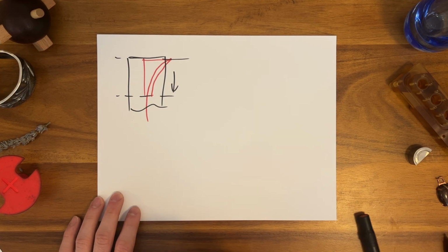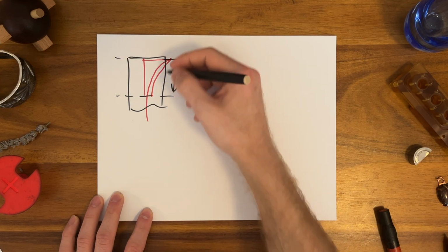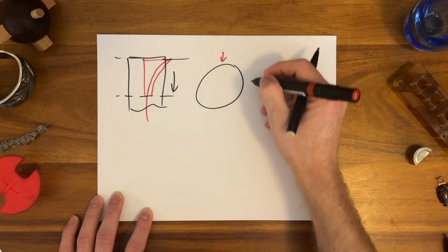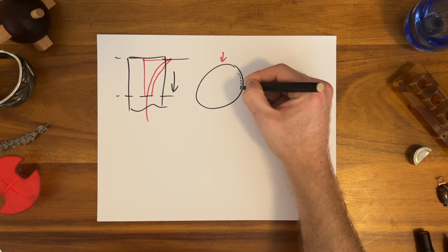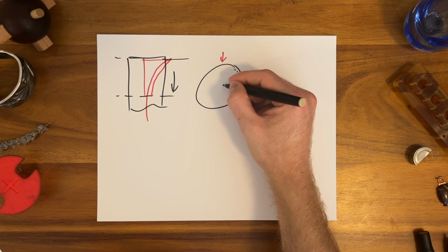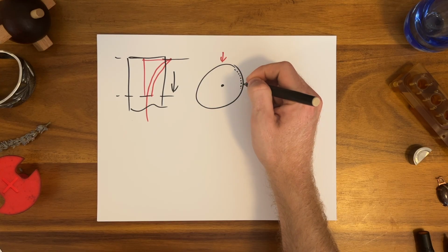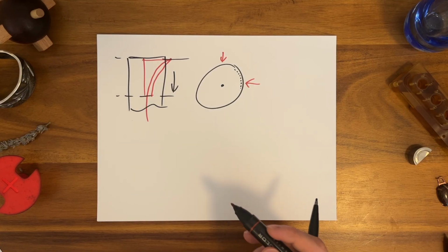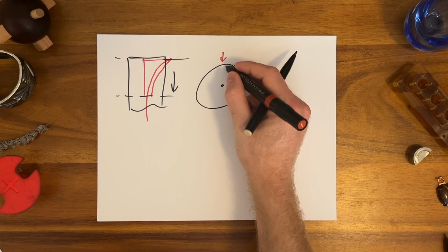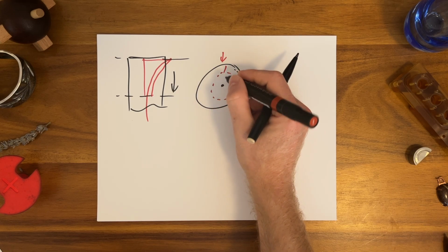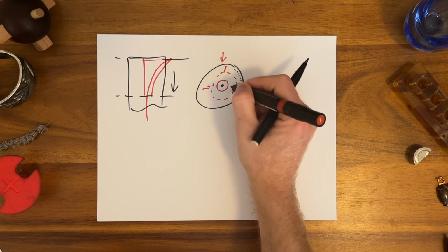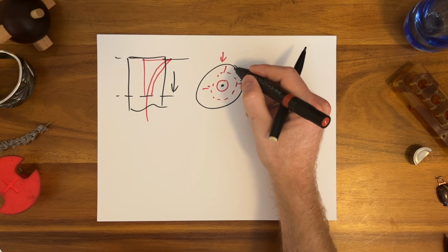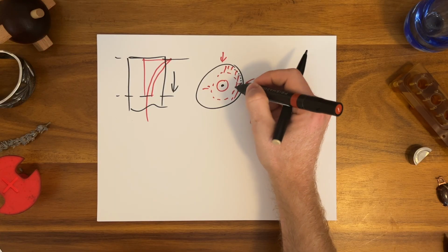So the other thing is shape and boundary condition also matter here. This is all kind of planar. If you have a cylinder and you're heating the outside, if you just barely heated the top few microns and you're looking at a really large Fourier number, you're way inside the part, it looks like a semi-infinite solid. But as your Fourier number gets smaller and smaller and smaller, and you are heating in from every single direction, all of a sudden the heat from here and the heat from there, like, wait a minute, I saw you last Thursday. They're all ganging up on a smaller and smaller amount of area. Clearly it took a lot of power to heat up this whole region, and it takes less and less and less.